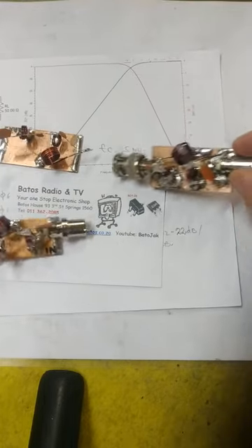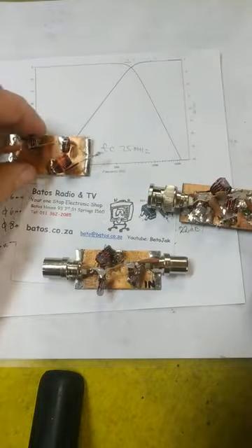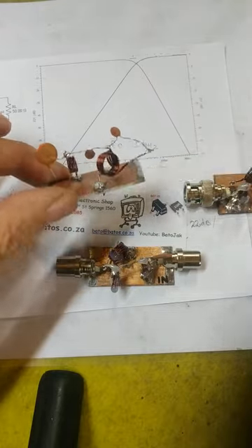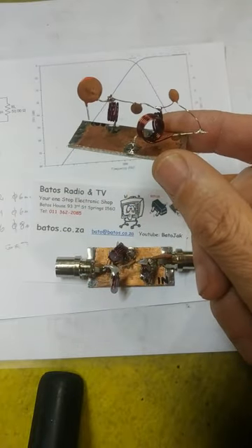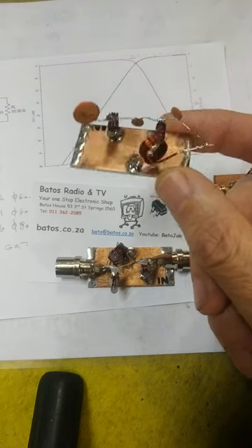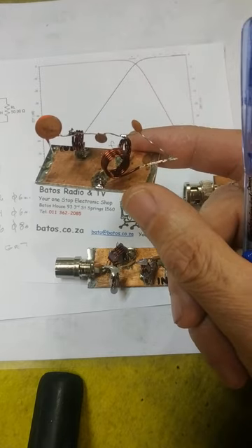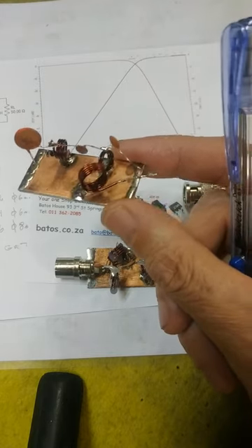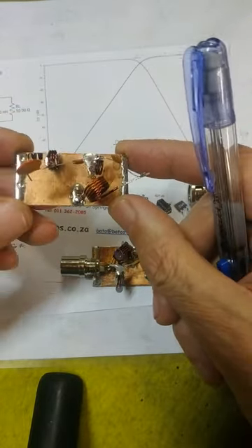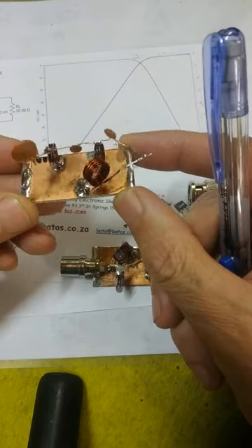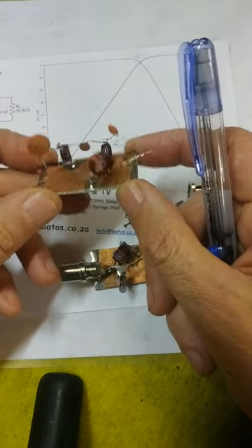And as I said, I've used different plugs, like BNCs, or even coaxial cables, or it can be soldered directly onto whatever circuitry you want, to attenuate everything below 75 megahertz. A typical application: I used it for filtering noise from switch mode power supplies, solar, PCs and so on, for FM radios in the FM band, anywhere from 88 megahertz up. It can also be used in airband radios, which is up to 130-something megahertz.